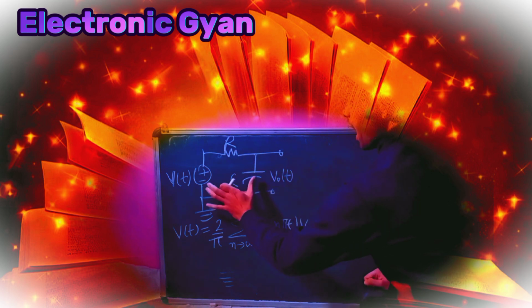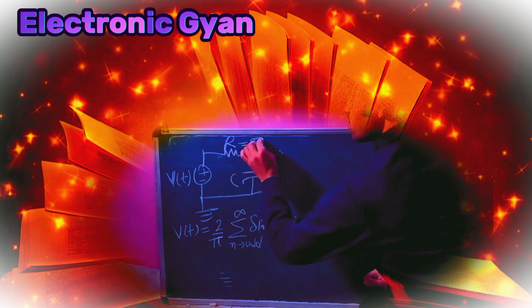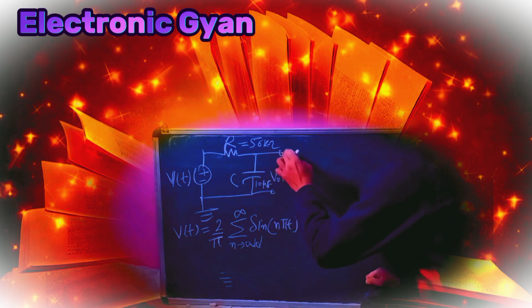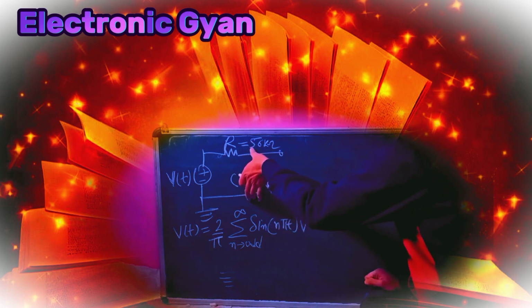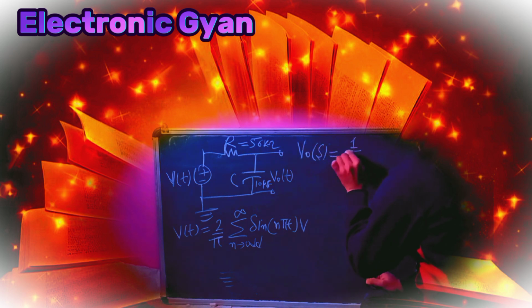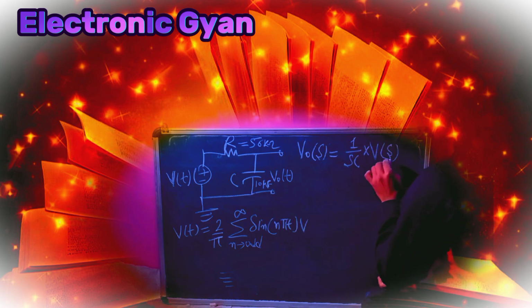Writing in the s domain, R is 50 kilo ohm, and C is 10 microfarad. By applying the voltage division rule across the capacitor, we get the output voltage V0(s) as 1 by sC multiplied by the input voltage V(s), divided by R plus 1 by sC.